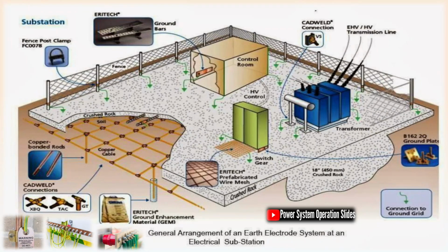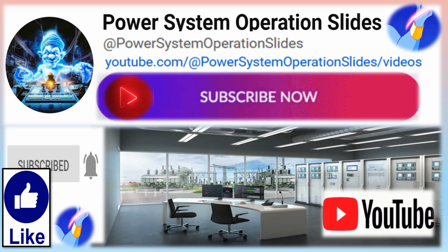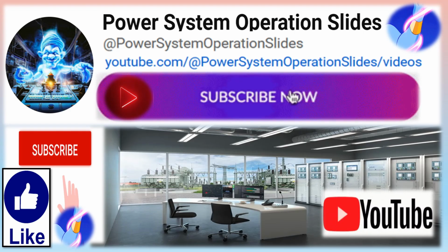Auxiliary relays. AUX relays multiply contacts, provide interlocking logic, and support tripping functions. They enable complex control circuits and SCADA interfacing. They are foundational components of protection schemes.